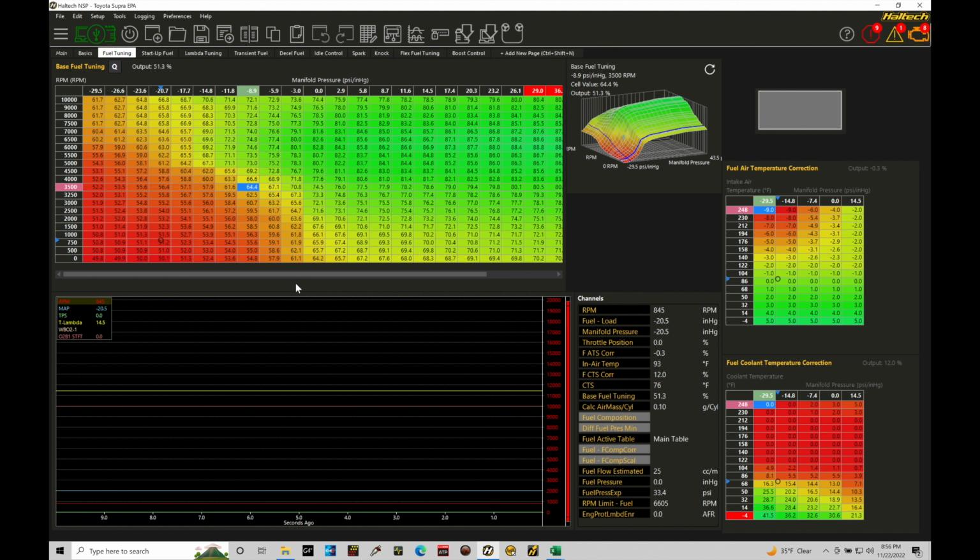My preferred way, and Haltech's base files that they always supply, are all going to be the speed density volumetric efficiency based tuning strategy. This is the more common and, in my opinion, best option to use when you're calibrating and working with your Elite system. It provides a mathematically based model so that we can have values in here that are not just arbitrary. We're not going to be just firing random numbers in here to increase or decrease our fuel. We are going to be very specific with our numbers, and we can do a check on our work.